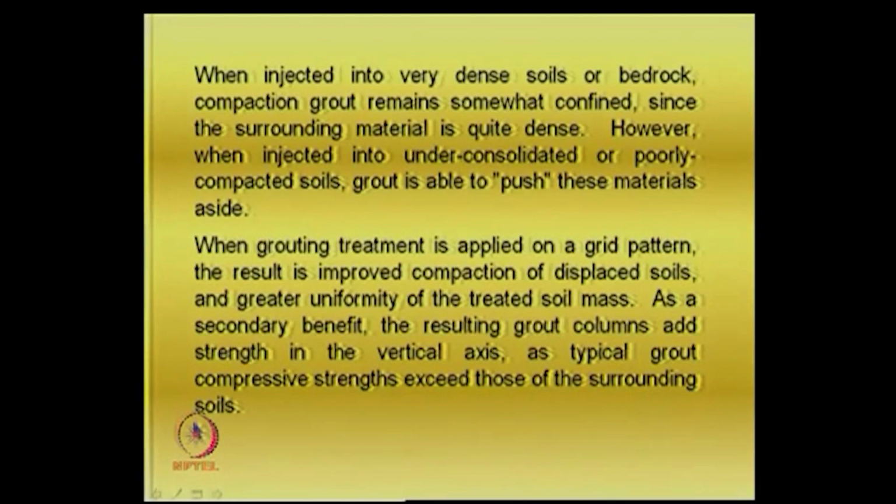We have seen that presentation by Keller, in which the objective is essentially to treat the ground in the form of a grid or whatever and improve the bearing capacity, but you also have the formation of columns here. The possibility is that the compressive strength of the grout could be much higher than the surrounding soil, and that can be used as a basis in which one can evaluate the bearing capacity improvement or settlement reduction. This is a very important point here.